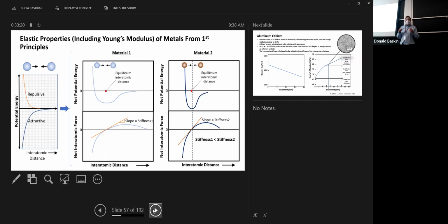So what you do is you start sizing this beam that's in cantilever, bigger to get to your load. You reach some point where it's thick enough to support your elephant. And then you find out that its natural frequency is too low. It's not meeting that design requirement. So you go a little bit further, until finally the beam is stiff enough that when the elephant wags his trunk, he doesn't shake it more than 20 hertz.